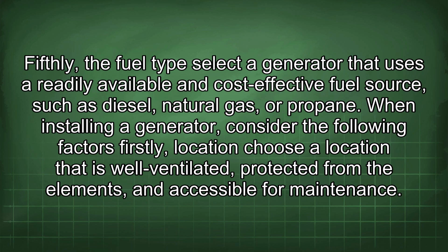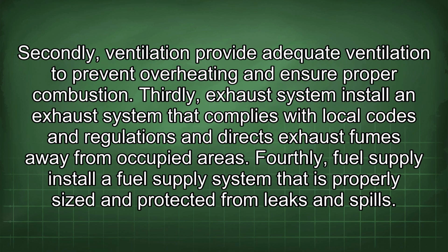gas, or propane. When installing a generator, consider the following factors. Firstly, location. Choose a location that is well ventilated, protected from the elements, and accessible for maintenance. Secondly, ventilation. Provide adequate ventilation to prevent overheating and ensure proper combustion. Thirdly, exhaust system. Install an exhaust system that complies with local codes and regulations and directs exhaust fumes away from